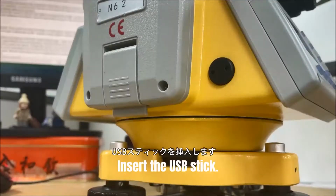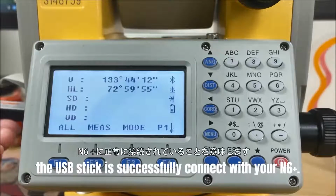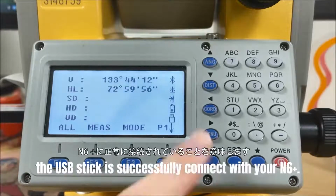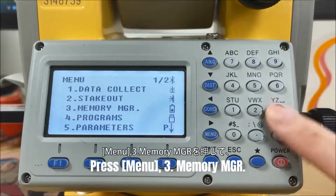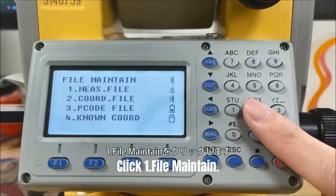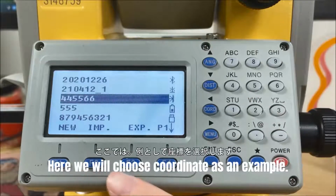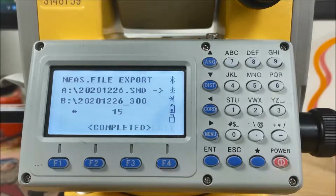It's easy to import and export data by USB. Insert the USB stick. An icon appears at the corner, which means the USB stick is successfully connected with your N6 Plus total station. Press Menu, select the third one, Memory Management. Click File Maintain. Here we will choose coordinate as an example. Click F2 to import or click F3 to export.